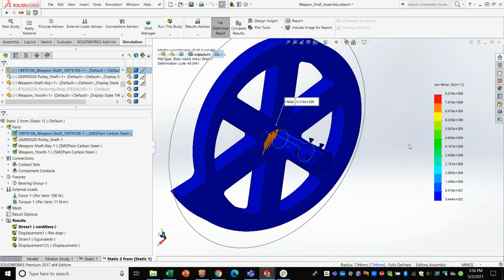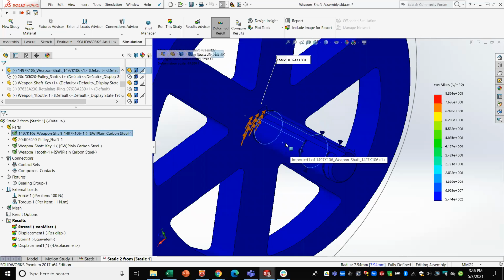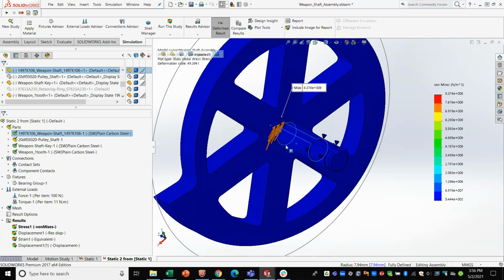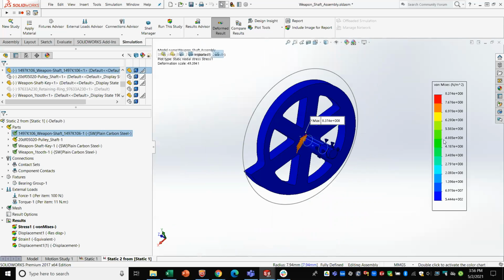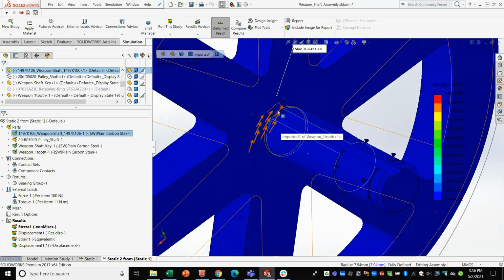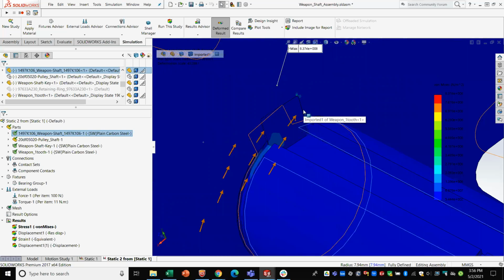You could calculate that rotational inertia and then impart it as extra mass on the shaft. You could give the shaft fake material properties to increase its moment of inertia, so that it would be representative of all the moments of inertia of everything downstream. And that would give you more accurate stresses in the keyway.